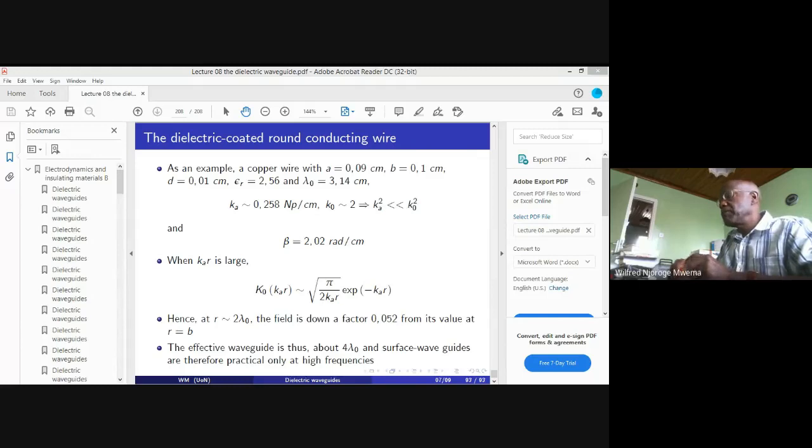Sometimes if the real part and the imaginary part are both negative, remember the tangent is going to be positive, but you must add pi to it as well, and therefore it will be between 180 and 270 degrees. So that's something you have to always keep in mind, especially if you get a problem asking you for the length of a transmission line that will be required to perform a given function. So with that, let's meet tomorrow and we'll talk about radiation.